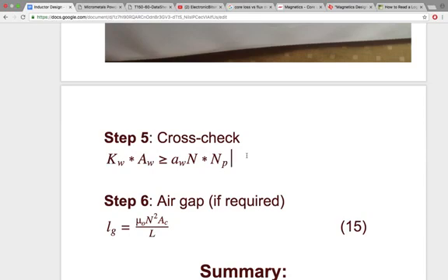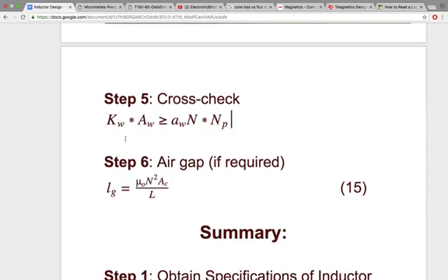So what we do is we can take wires of current rating like 5 ampere or 10 ampere, and we can connect them in parallel, and hence winding them over the core becomes much easier compared to winding a 100 ampere wire. So this formula we can again use for DC and AC. If there is just one wire you have used, not a parallel bunch of wires, you can make NP as 1. This will work for both cases.